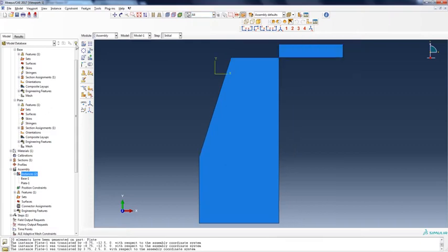Okay, then when we translate it again, but this time we are going to use a different method. Constraint edge to edge. Yep, so now it's shifted to the left. So this is where they are on the same axis. This is where we want it to be.